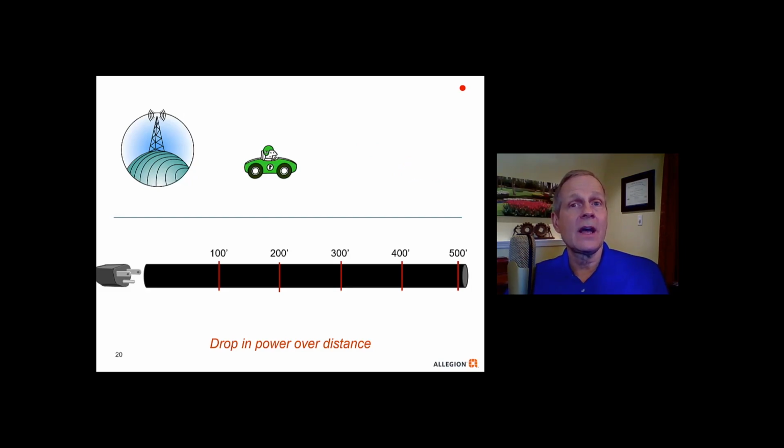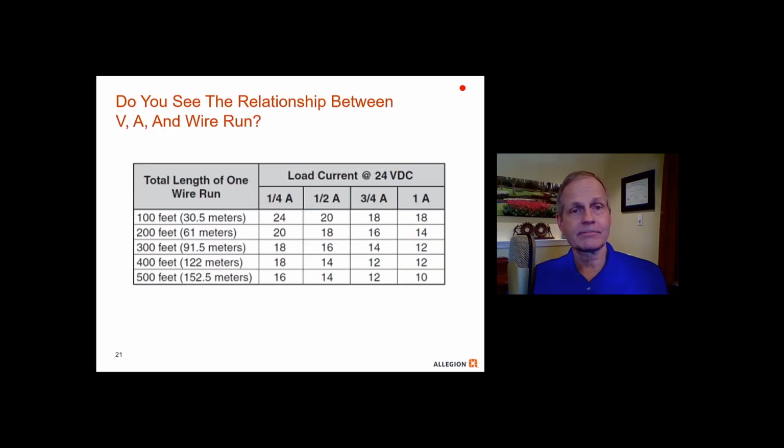When you transmit voltages over longer distances or longer wire runs, there's going to be something called a voltage drop. And you're going to need to take that into consideration when you are choosing your conductors. Generally, the longer the distance of the wire run, the larger the diameter the wire needs to be to overcome that loss that is caused due to resistance.